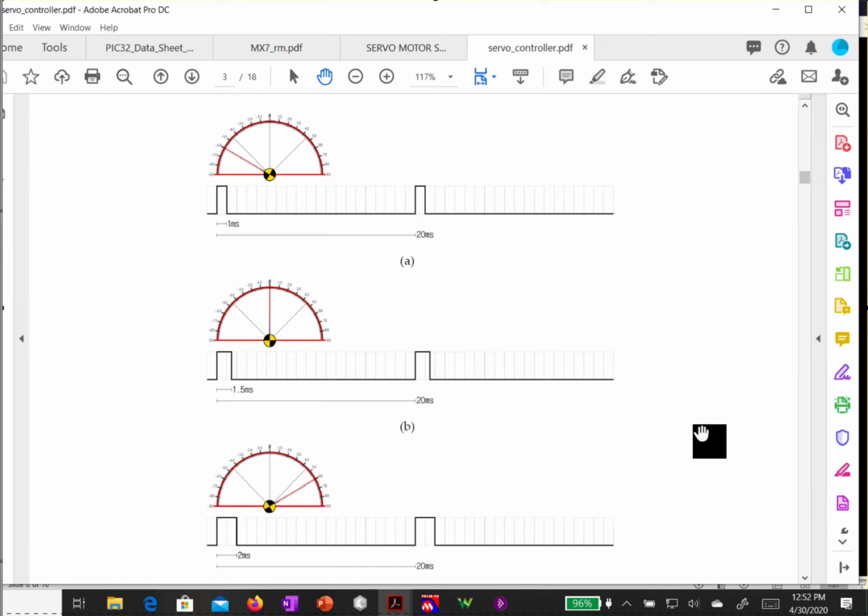And so we have a different strategy that we're going to use for this system. First thing we need to do is have a synchronization. We need to provide these signals every 20 milliseconds. So if I think about it, I want to control 8 motors, and let's say that they're all fully to the right. So I need 8 pulses of 2 milliseconds, so that's 16 milliseconds. So I still have a little bit of leeway, so I could control 8 motors if I could do them in sequence. If I do motor 1 for the first 2 milliseconds, motor 2 for the next 2, and so on, and I have them all synchronized to this 20 millisecond time, then I can do that.